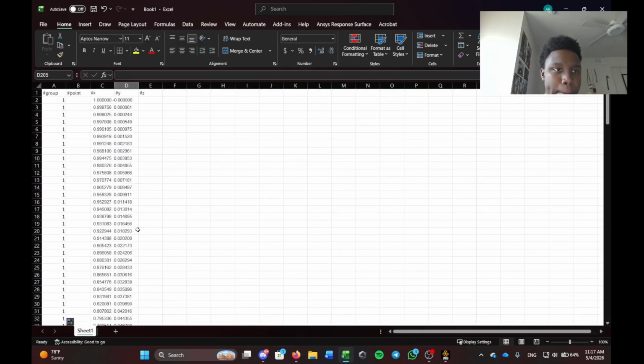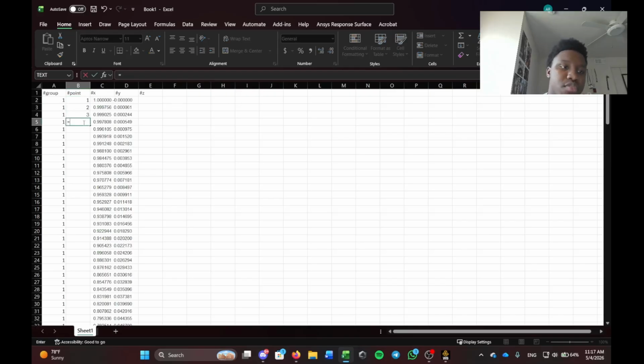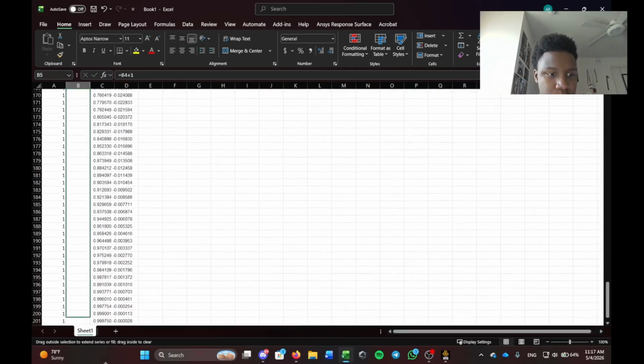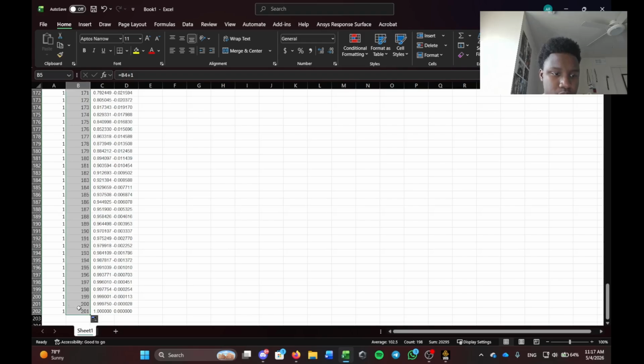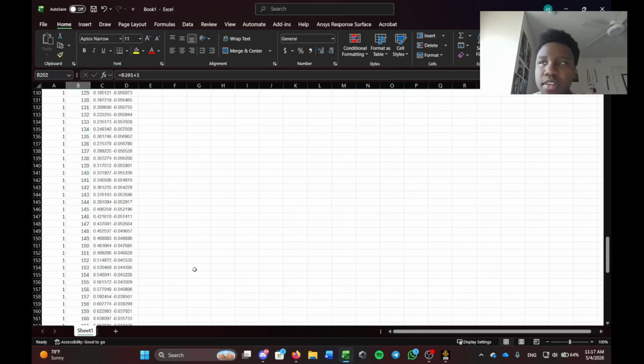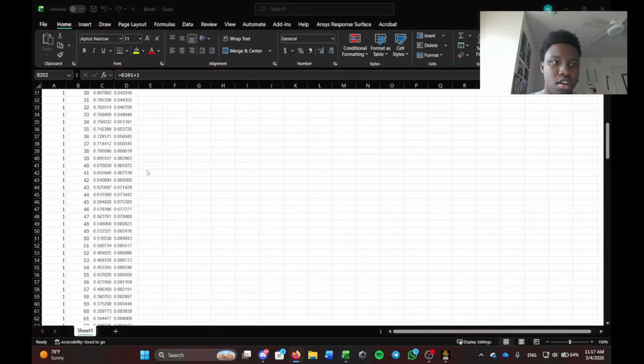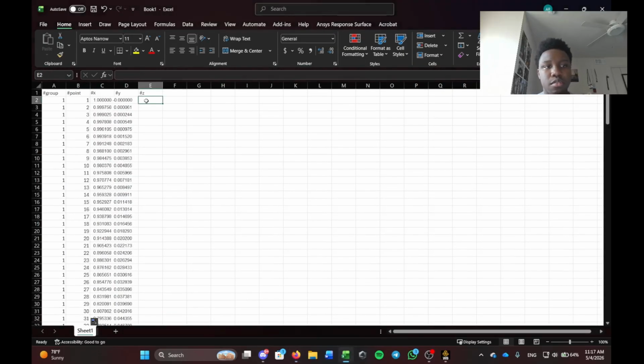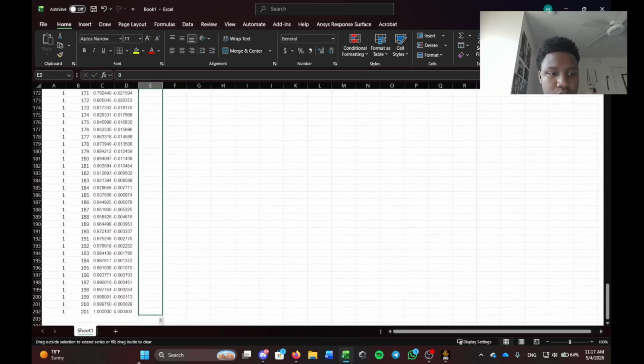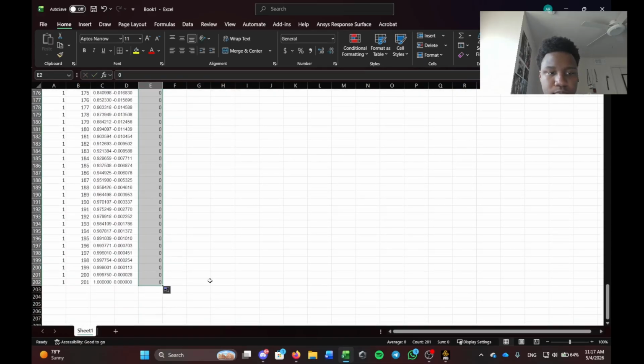Go back up here. For points, we have 200 points that we're going to start at 1, then we go 2, then we go 3. And then to make this easier on ourselves, we make our little formula here, equals, click the cell above, plus 1. Drag that filler down. Boom. As you see, we're at 201 points. We're going to fix that a little later. And then when it comes to the Z over here, since we're only working in the XY plane, Z is going to be 0. And then you do that right there. Boom. Alright.